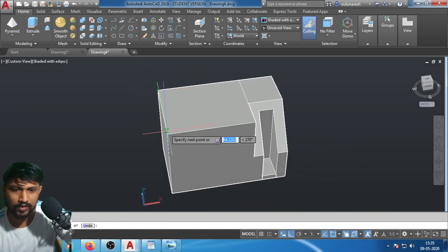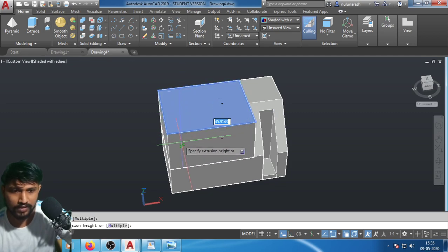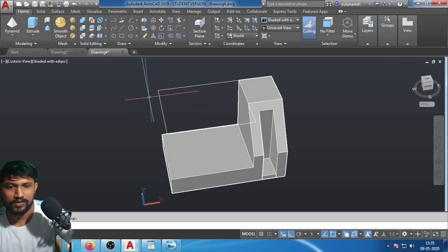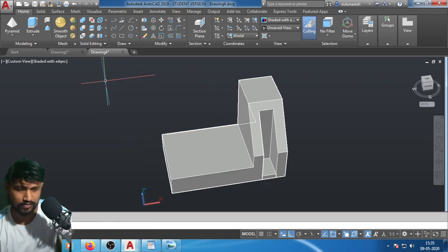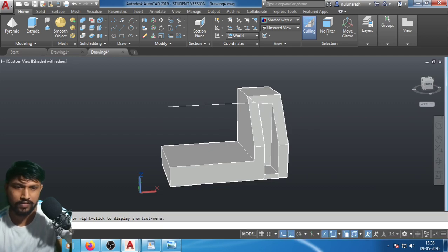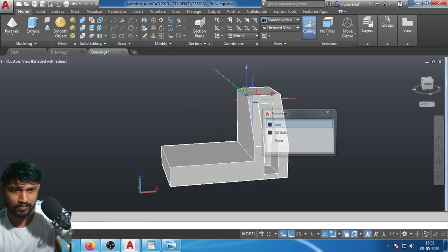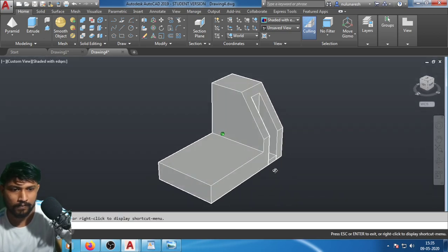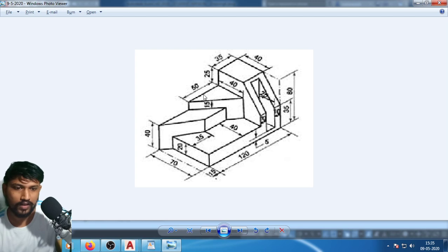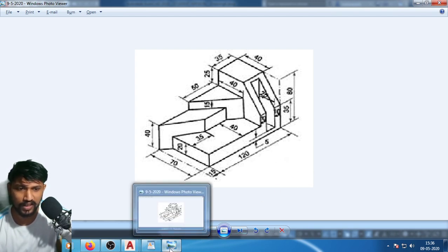So now what I'm gonna do is take this dimension up to 20 mm of dimension, so which means 60, which means I have removed the portion that I've created. Now I need to create this additional geometry. By the way, the arrow is not actually given. I will take the arrow the way I actually want to, and after that I'll draw the front view, top view and side views of this one.